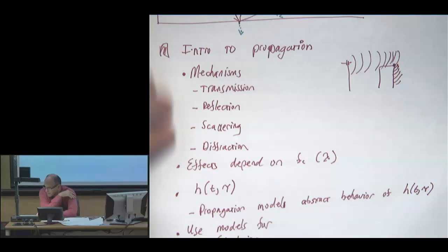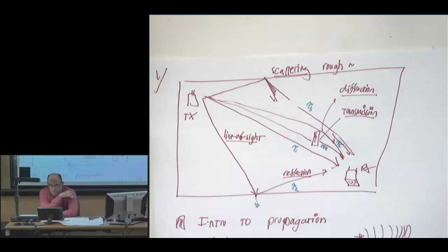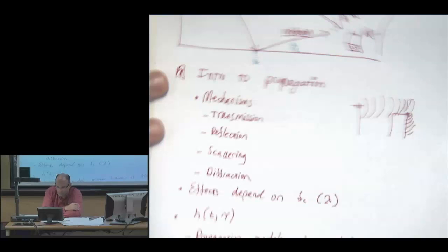We want to do all of this because we do not want to design a wireless system that just works in this room that I've illustrated here. We want it to work in a lot of rooms. But we don't necessarily want it to work everywhere, because that might be too much of an unconstrained problem. For example, we might want a wireless LAN to work well in office spaces and in homes, but we might not care if it works well way down in the berths of a large tanker ship that's got a lot of metal. Maybe that's not a priority there. It would be a lot harder to make wireless work in a big metal ship. So we come up with models that reflect the different set of possible propagation scenarios that we can see. Sometimes you're right next to the transmitter. Sometimes you're further away. Sometimes you're around the corner and you're getting a reflected signal. So the models are generally there to capture these different scenarios.